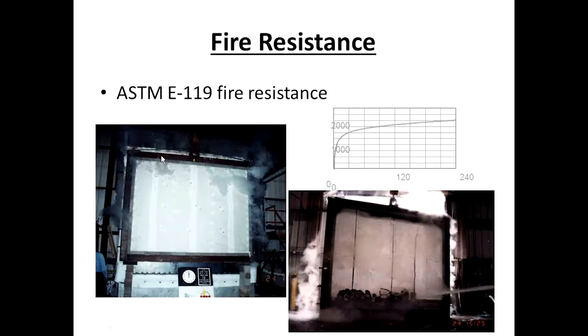What you're looking at here is a concrete and steel yoke. We build a wall. That's what you're looking at here. The size of this yoke is 100 square feet as required by ASTM E119. Nominal 10 foot by 10 foot, and you can see this is the wall board underneath it because of the joints. You can pick out where the framing members are. So this wall is built exactly as you would want it to be, let's say, in a real life event. So behind it are metal studs at 16 or 24 inches on center. There's a track at the head, a track at the base, and wall board assumably on the other side.